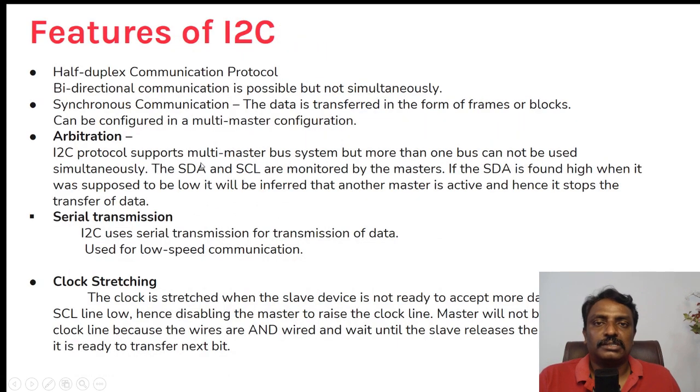And the features: it's half duplex. Bidirectional communication is possible but not simultaneously. It's a synchronous communication, based on the clock. And it has arbitration: if any master communicates, the other can understand it and stops transmitting the data.